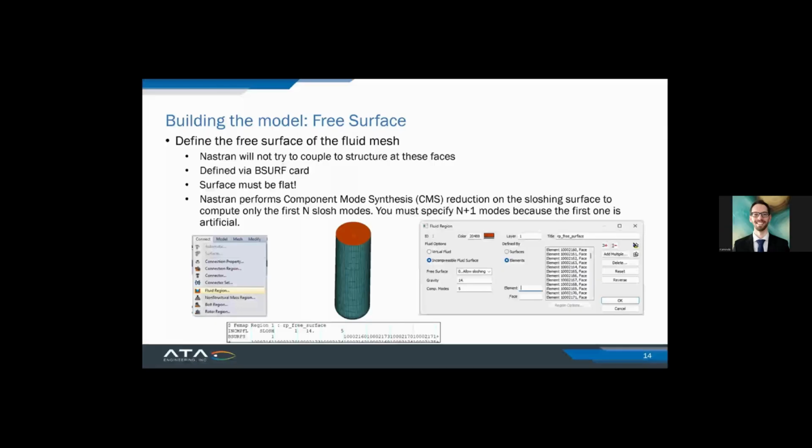All right. We had another question from Aditya. Let's see. I have this method of slosh modeling in my tank, and have made an external super element out of the tank. The modal effective mass looks realistic for the tanks in the individual model as well as the global Sol 103 model. But is there any way to confirm the slosh modes are behaving properly besides looking at the SPC force PSD?